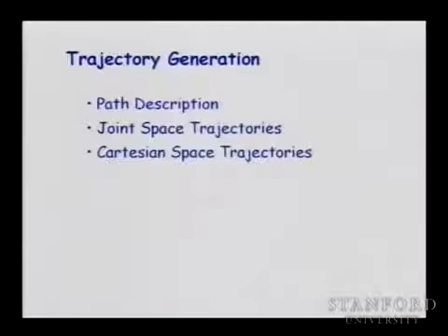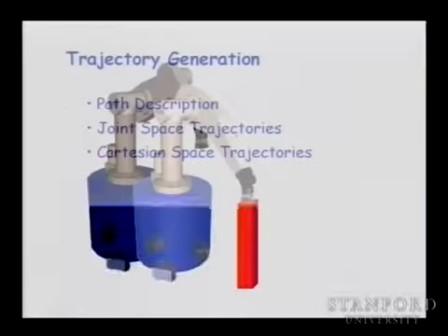And then using those solutions, we can do this interpolation between where the robot is at a given point and then how to move the robot to the final configuration through trajectories that are smooth both in velocity and acceleration and other constraints that we might impose, through the generation of trajectories both in joint space and in Cartesian space.